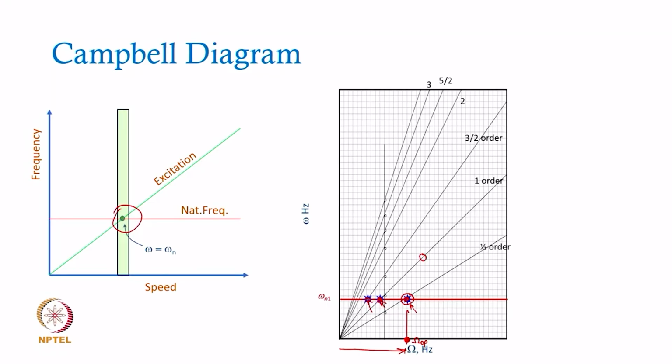So, these resonances are actually secondary resonances, or resonances generated because of the closeness of higher frequencies of the same excitation function. The primary frequency or the fundamental frequency of excitation is still this, and this resonance is the main resonance. But when I am approaching the operating speed from 0 operating speed, I will be crossing multiple resonances as I have shown here, okay.